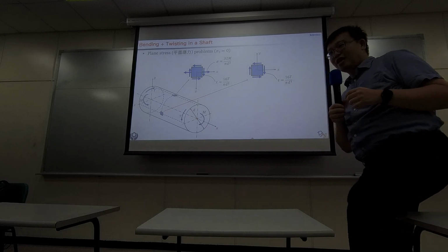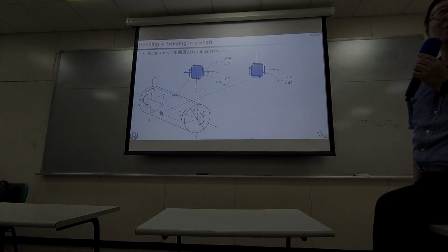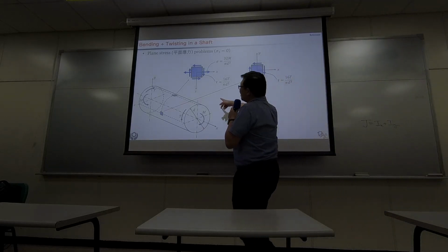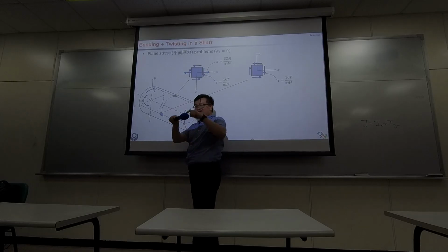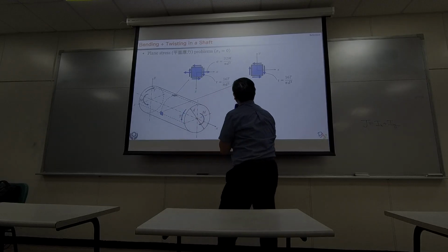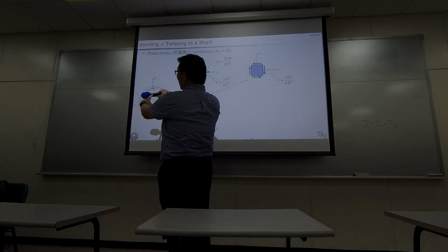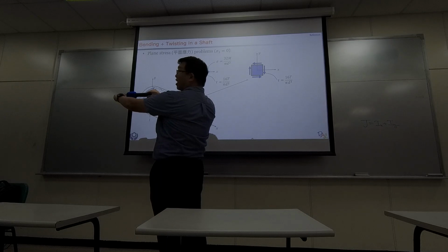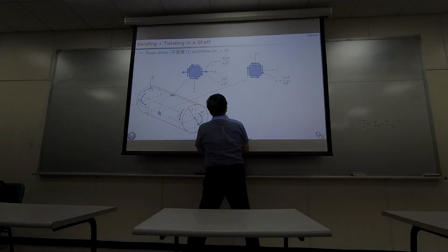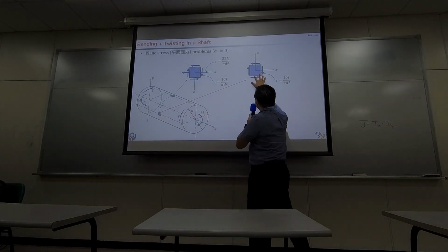So, for this particular material, if you had some kind of device that visualizes the force, you would see a drawing like this. But there's nothing like this in real life. But anyway, that's how the force is applied on the top of this shaft if you bend and twist simultaneously. How about the point on the side? Because it's on the side and lying on the neutral plane for bending, there are actually no forces left to right. So over here there are no horizontal forces, but the twisting is still there. So the same amount of twisting.